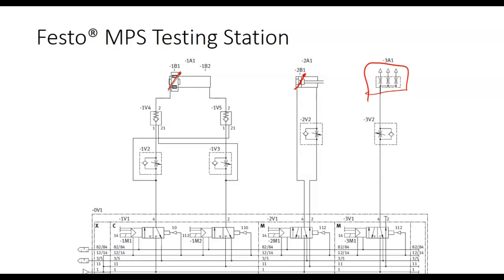So anything else? Oh yeah, this does the same thing. They just do it in the opposite direction. So here's their check valves up here to keep it from bleeding back when we put pressure on both sides. This is pilot assist. So they actually use that, they just do it real big. Solenoid operated pilot assist with a manual override. This is very unusual. This is the first time I've ever seen this.